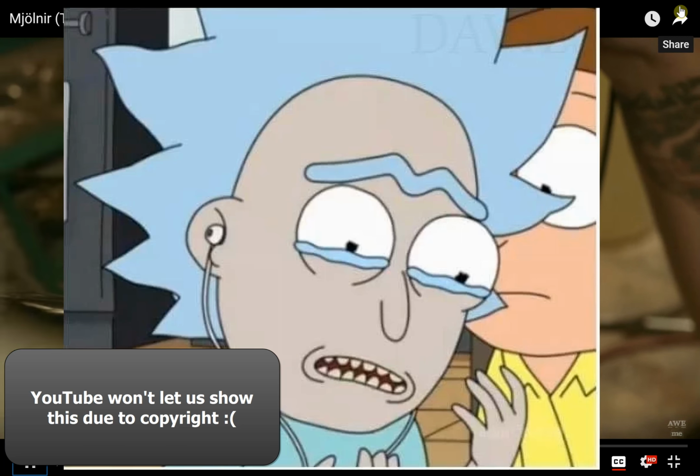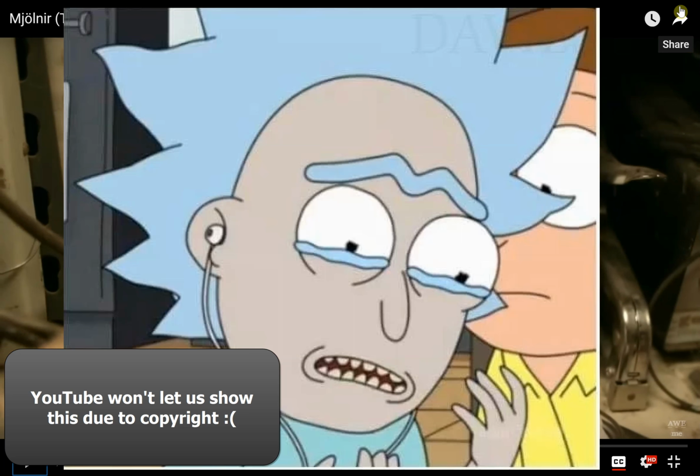So they take the polymer resin silkscreen, which they use with the UV light source to put that pattern on that vellum. Here it's going to be a DC driving force. You hit the DC button as opposed to AC, because what they want to do is etch in one direction. They don't want to apply ions and pull them away, apply ions and pull them away. They just want to continually etch away in certain spots. So he's going to apply a DC current.